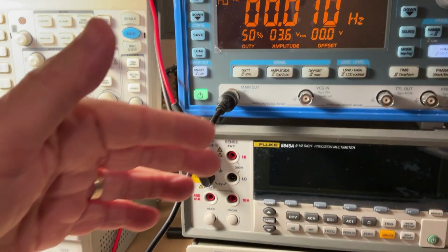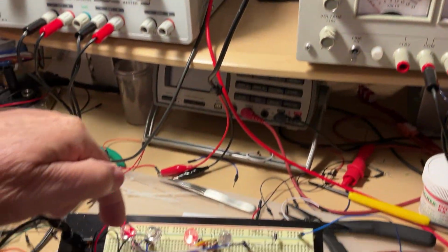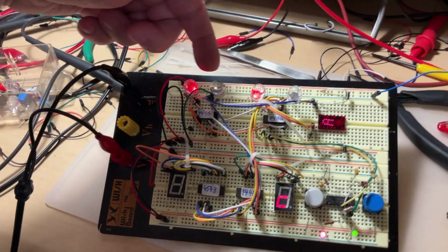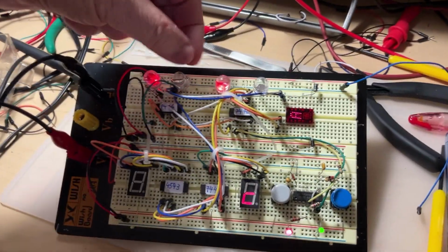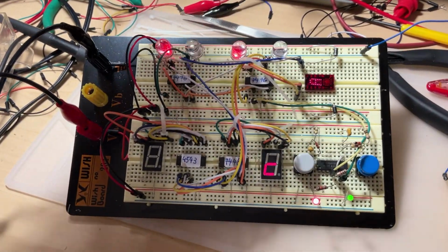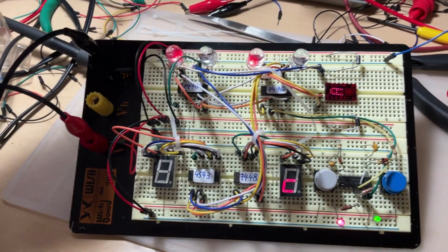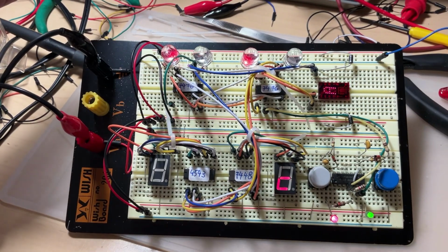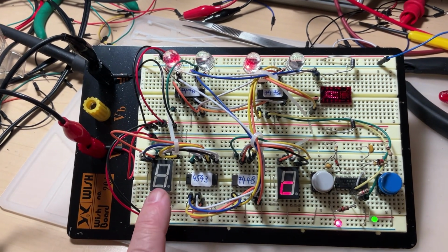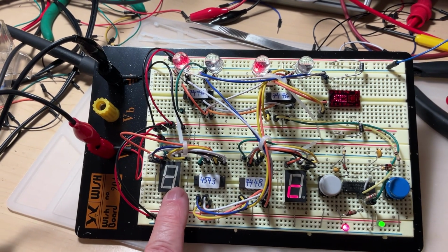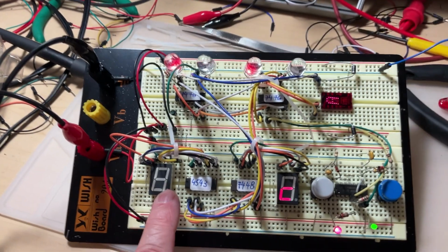But what happens if you give the binary signals to these decoders also on 4 bits, they are still on 4 bits, but the combination in binary goes over the number 9? What's going to happen? This kind of display refuses to show any number if the combination in binary goes bigger than 1001.